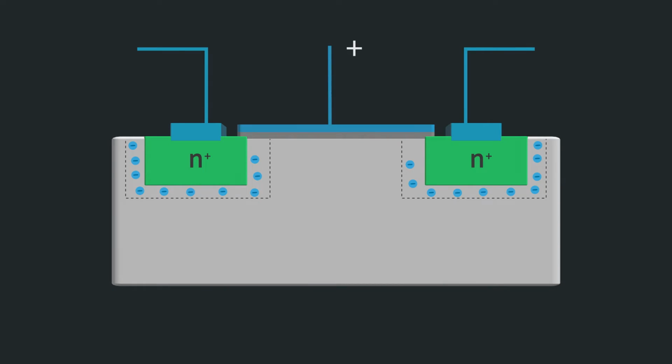If you increase the gate voltage, that positive voltage will repel holes in the substrate away from the area between the source and drain, an area called the channel region, this time a physical region. As the free holes leave the channel, only negative fixed ions are left, creating a depletion region across the entire channel. Besides this depletion region, an inversion layer of electrons starts to form at the source, and as the voltage increases, that inversion layer expands toward the drain.